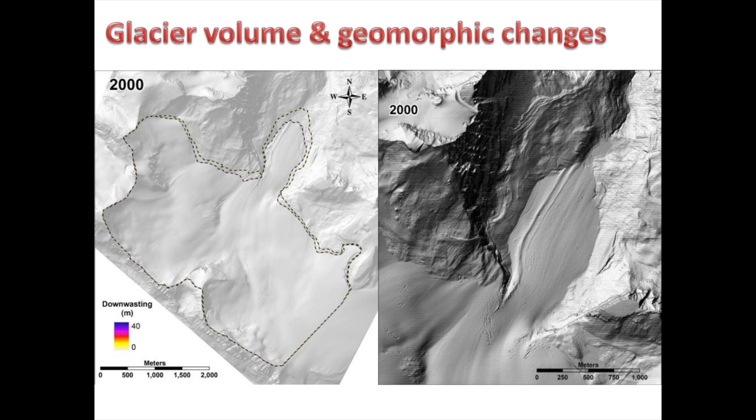And we can also see that the slopes around the side of the lateral moraines around the side of the glacier are actually sliding down or slumping in towards those margins. So with time series analyses from LiDAR, we're actually able to get some very high resolution and high fidelity information on morphological changes. We can measure the rates of changes and we can measure the volumes of changes.